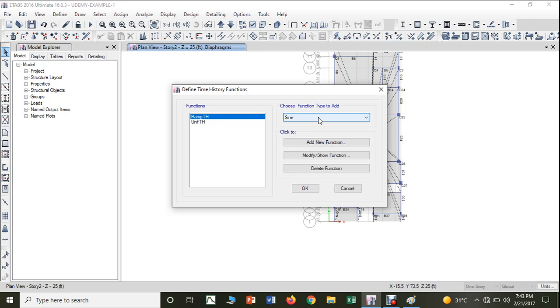That's why there is another advanced level also, what we call as liquid structure interaction, along with the soil structure interaction, because the dam has to have the interaction with the liquid also, that is the water which is going to be stored. A very huge amount of pressure will be acting on the dam. So therefore there you are supposed to consider the soil structure interaction also, and the liquid structure interaction also.